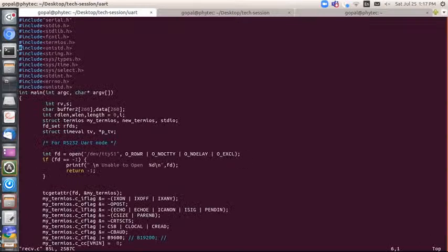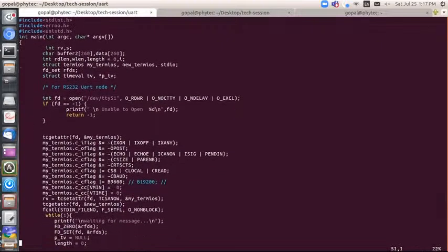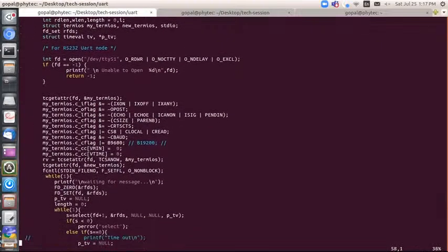The other program, now I can show you one more here, the receiver, the recv.c program. You can observe straight away that I didn't use all the options to configure the port. I just enabled software flow control and parity, and here we have the baud rates, then the number of characters and the waiting time to get the characters. We just configured what is sufficient.